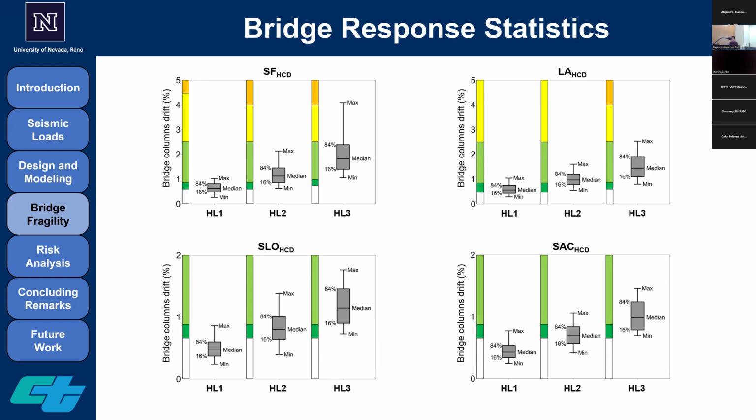We have a response that is consistent with the design that we have already adopted, which is a hazard-consistent design. And we have consistency even when we go below 1% reinforcement in our model, which is for two locations: hazard levels HL1 and 2 in LA, and HL1 to 3 for San Luis and Sacramento. So we are trying to show that by relaxing the code's criteria, we could achieve a safe, hazard-consistent design that withstands within the range DS1 and DS2, which is the repairable damage that we want for our models.